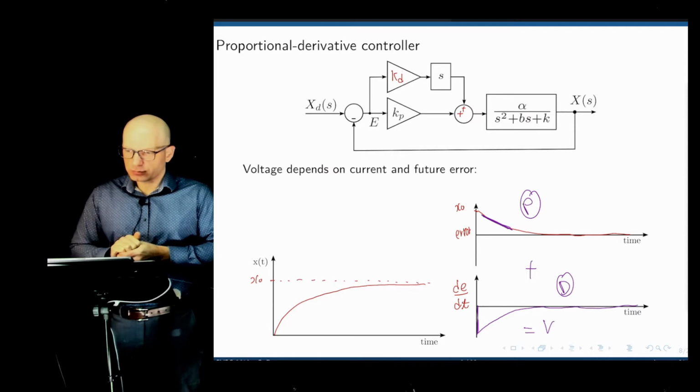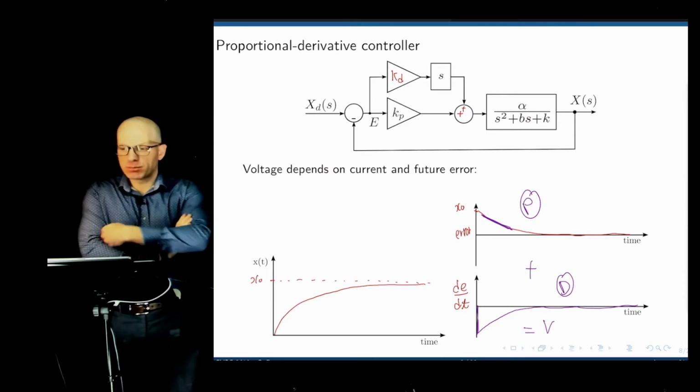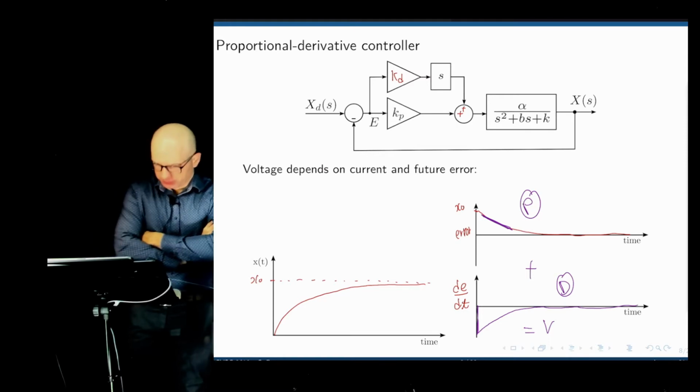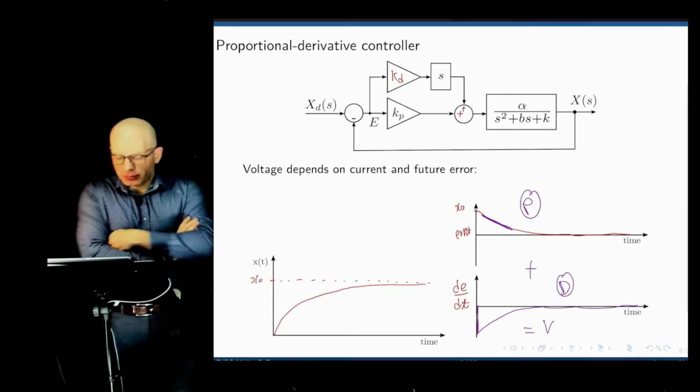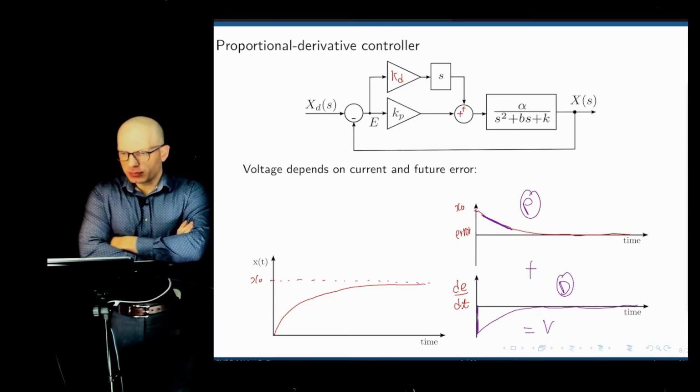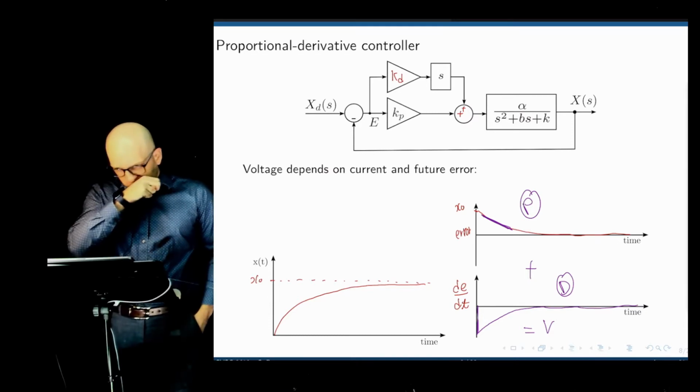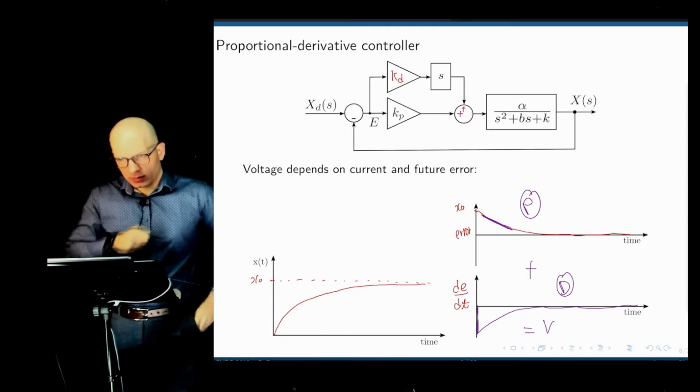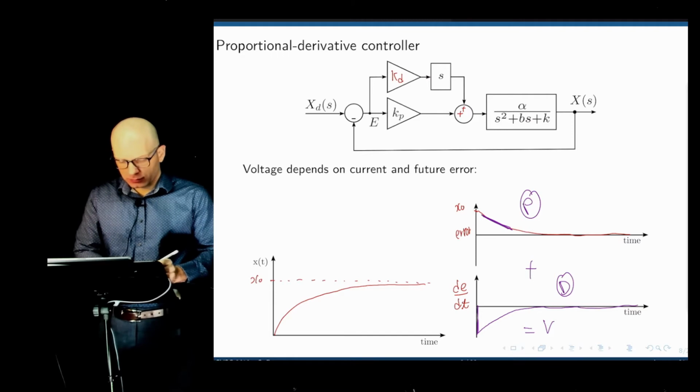Sorry, can I ask a question? Mm-hmm. I understand why it eliminates the overshoot, but I don't get how it makes our error actually become zero. Because we said if we have only the proportional controller, it never becomes zero. But here, for example, in this very example, we have only proportional and derivative controllers, and we can see that the error actually became zero.